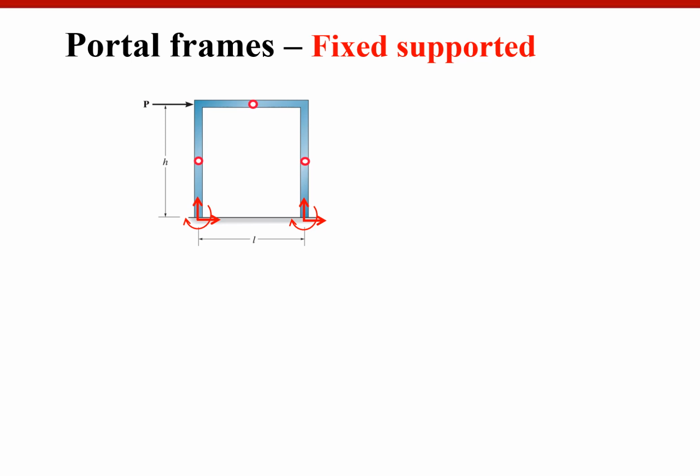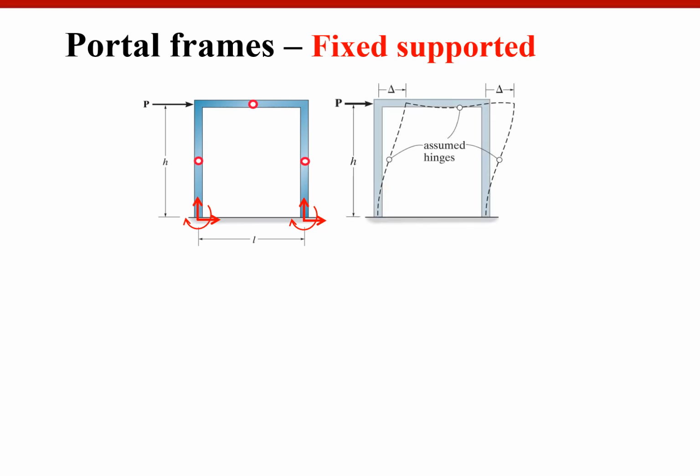The reason is, if it's a fixed support, then the deflected shape of the column has this double curvature, like the beam as we discussed, and this column has the same deflected shape as the left column, so that approximately at mid-height of the column we are going to have an inflection point, and the location is very close to the exact solution. Okay, and memorize the location of the inflection point, even though that is approximate, but very close to the practical case.